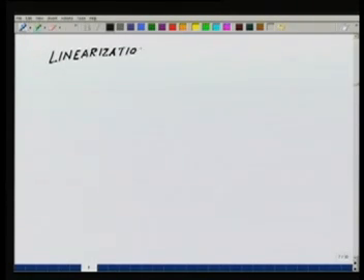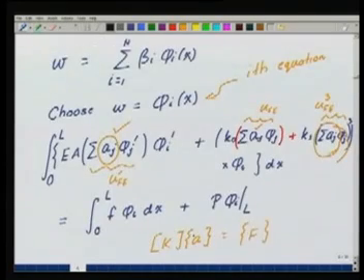What is the basic idea here? Okay, so we will use an iterative solution technique in this, because it cannot be written in this form directly. You cannot get a solution vector A by simply inverting K, because now K will also be a function of A itself. So we have to make a guess, start from the guess, go to the next solution, go to the next solution. So we have to solve iteratively. So, iterative solution.